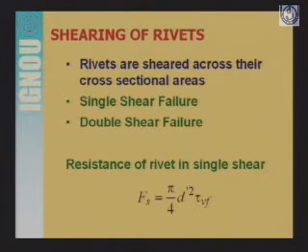Now under the load, what will be the resistance of rivet in single shear? Resistance of rivet will be the effective area in bearing that shear force, direct shear, into the shearing stress of the rivet. If we look at this formula, this Fs is the shearing resistance of rivet.